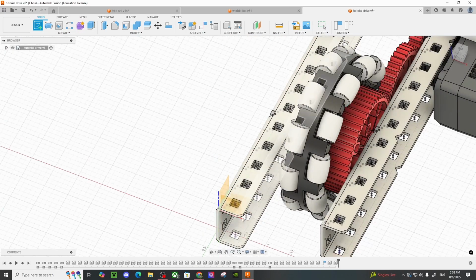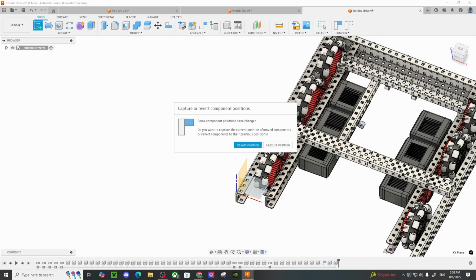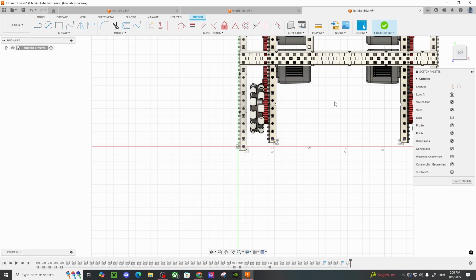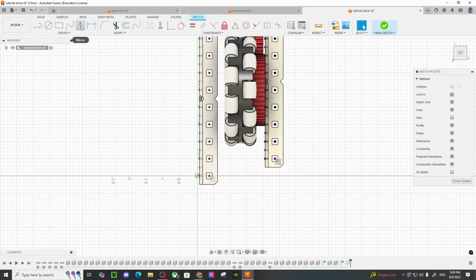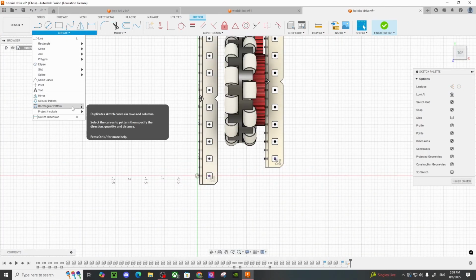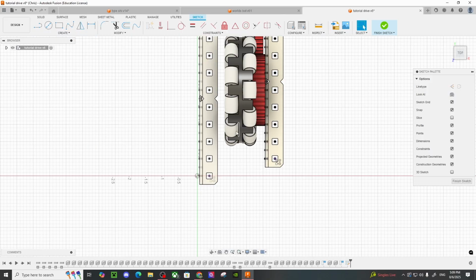Create a sketch and have it top down, so bird's eye. Step one is to identify where you want your screws, axles, or corners. Figure out where you want the screw inserts in your plastic piece, where your holes are, where you want screws, axles, or standoffs to go through, as well as where you want the corners of the plastic piece to be.